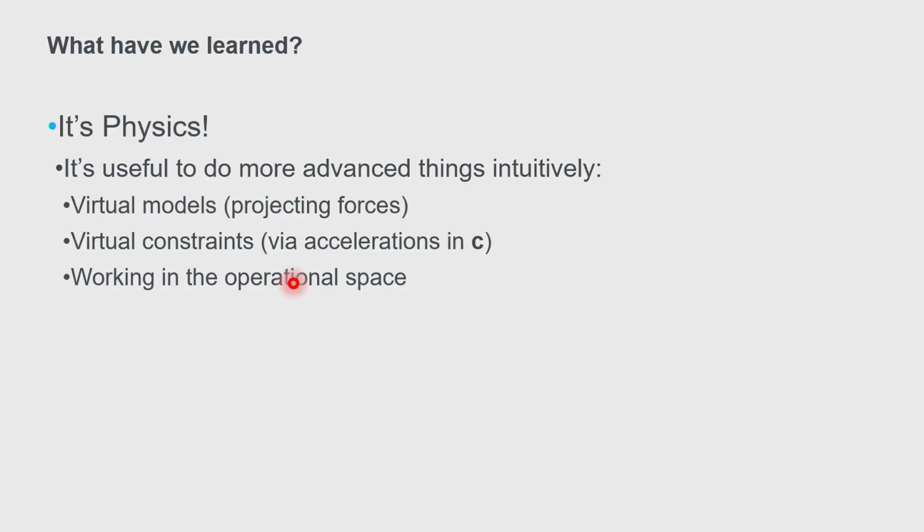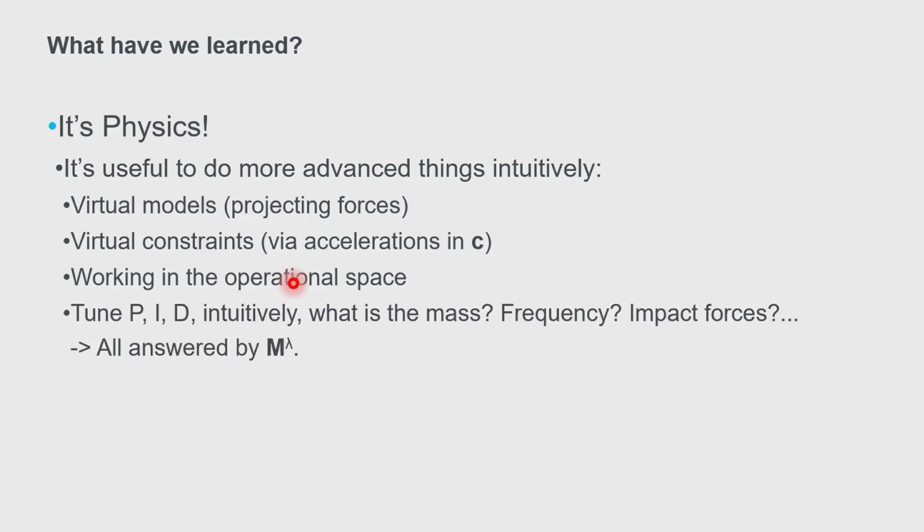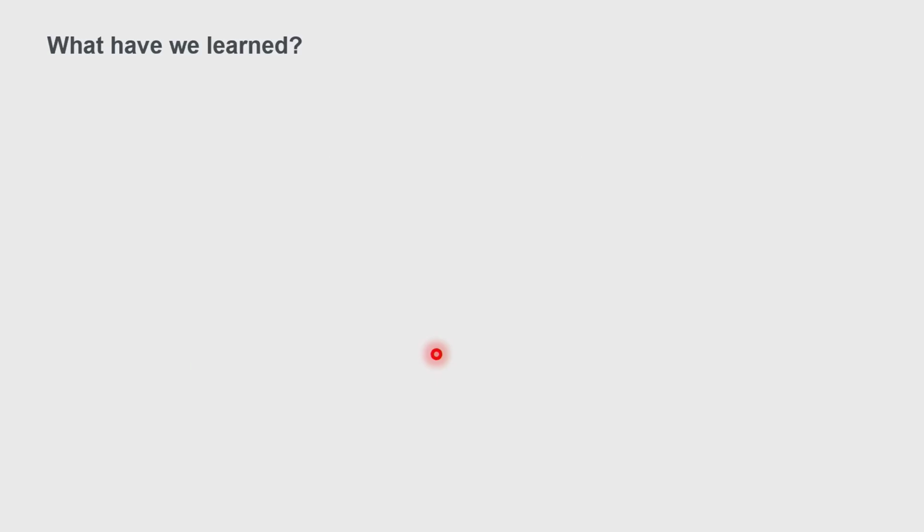There's a weird mass associated with it, which basically just means if I move in this operational space around this axis, that's the mass that I'm going to feel, and so on. And that becomes important when you start thinking about tuning gains, getting certain responses. As a control engineer, you always want to know what's your mass. And here the mass depends on what's the space you're working in. Is it joint space? Is it constraint space? Is it operational space, Cartesian space, and so on?